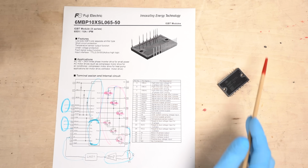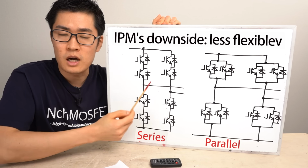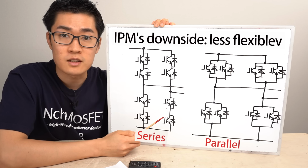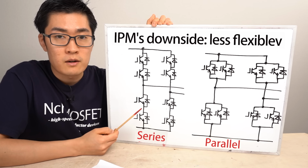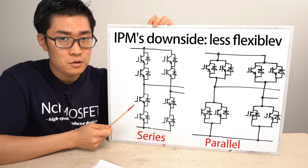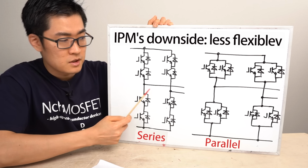So one of the key advantages of an IPM is that it has built-in drive circuits, which makes it easy to use. So far, IPMs might look like they have a lot of advantages, but there are some downsides as well. One of them is that they're not as flexible as discrete power semiconductors or conventional power modules. For example, with discrete power semiconductors, you can increase the voltage rating or current capacity by connecting devices in series or in parallel. With IPMs, however, this is basically not possible.